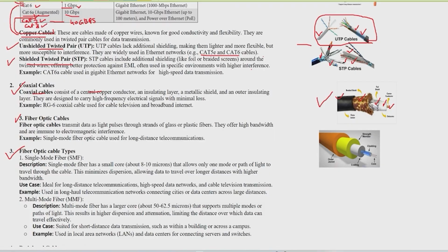For example, category 7, if you are buying 1 meter with 10 dirham, that will be maybe 30 dirham. So 2 to 3 times, 5 times costlier will be there. And the other problem with this is it is not bendable. The twisted pair cables we can easily bend, we can move through the holes and all that. But if you have to move 10 coaxial cables, that will become wood. You cannot move it. So the two problems with that: one is cost and one is their structure.